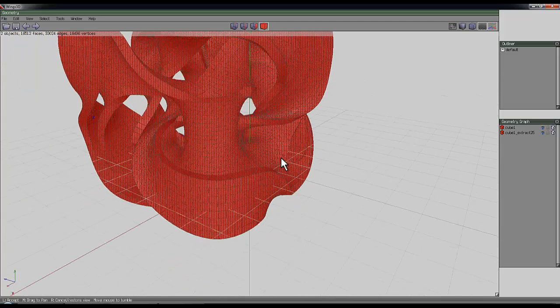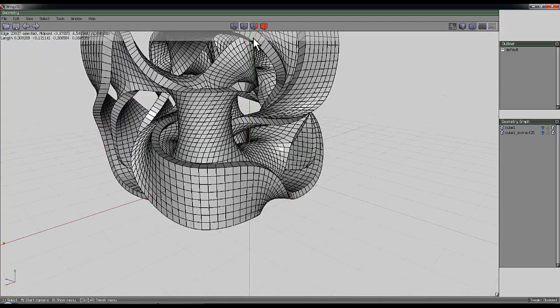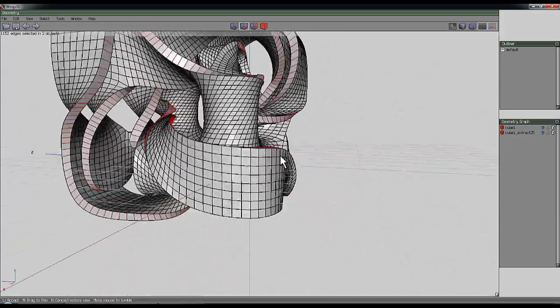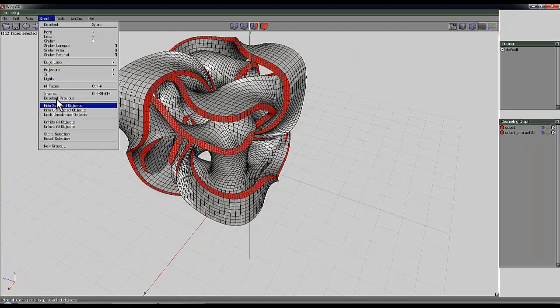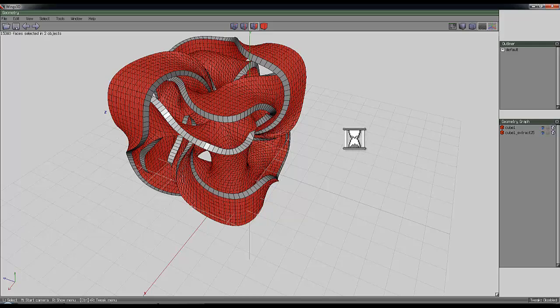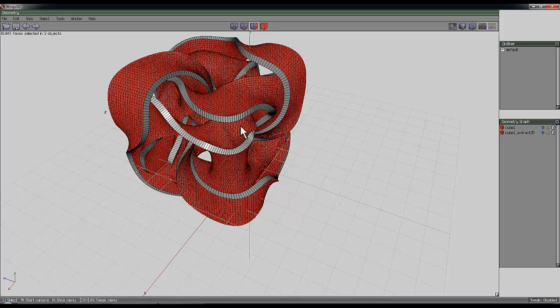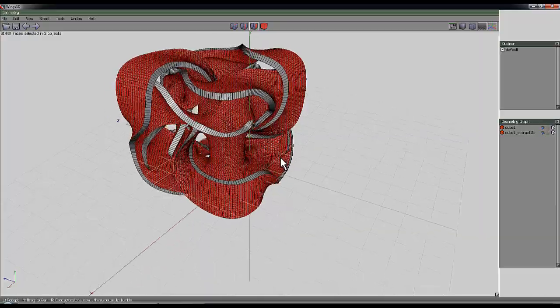And I was going to leave the edge fairly sharp, so if I use G on the inside of these, I'll just try and make sure I've got all of them selected. That's all those edges selected. Select the face, select inverse, smooth the faces down again, but that'll leave the edges sharper.